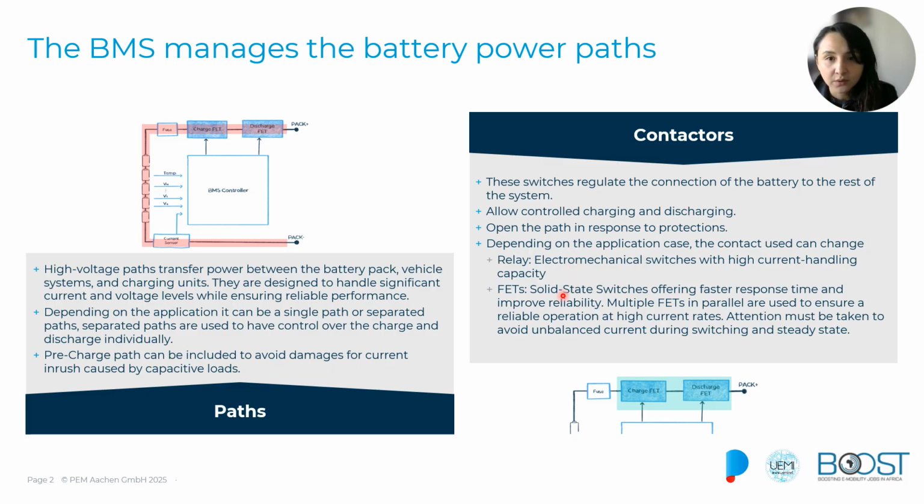On the other side, we also have FETs, and the FETs are solid state switching devices. They have a greater reliability, and for instance several of these devices can be used in parallel to handle high currents. However, they require a very precise design in order to make sure that all of these elements in parallel are sharing the same current, and also they are a little bit more pricey.